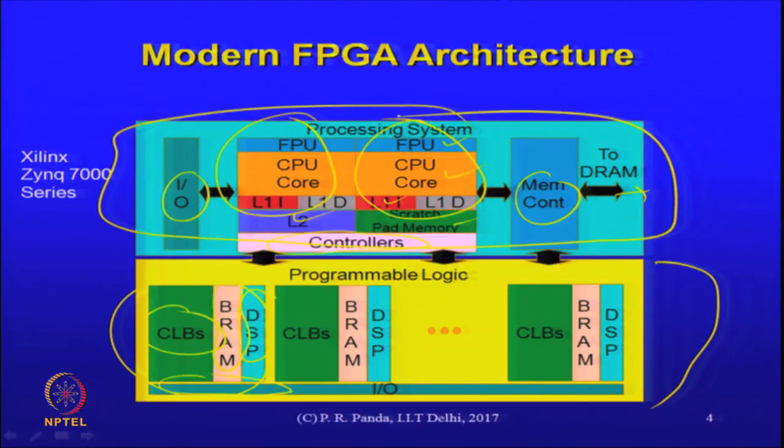So, these are what a typical processor environment looks like. But you might have a couple of processor cores or any number of processor cores embedded inside the FPGA fabric to help with all kinds of features. Essentially, if you want to implement a design in which part of the component is there in software, part of the component is there in hardware, then this kind of an architecture helps us implement that in a reasonable way.